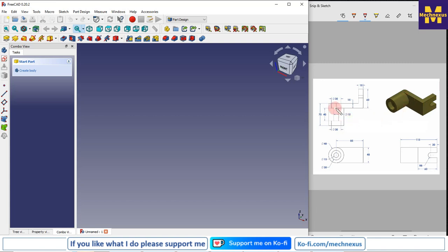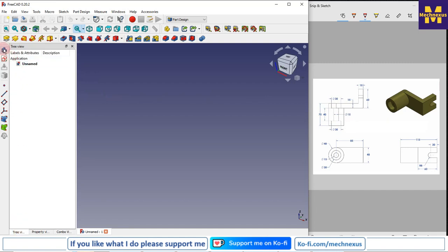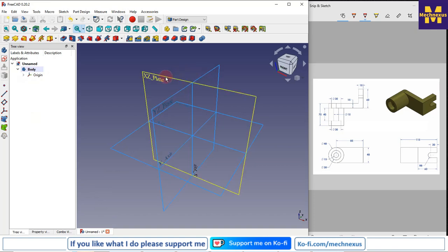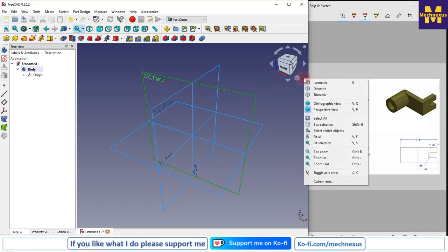So first we will make this circular boss, and we can see the hidden dimensions as well here. So let's start. First I will create a body, and I will go on my origin plane, and I will make it on the XZ plane, which is our front plane.